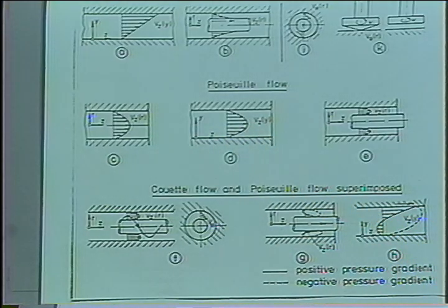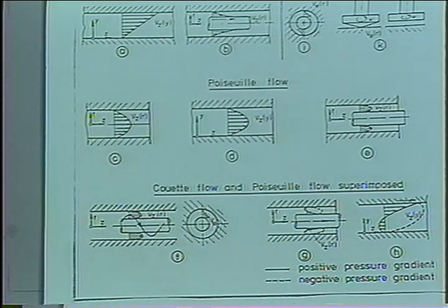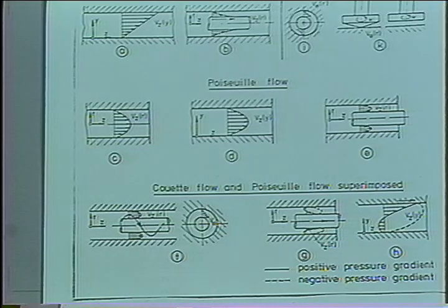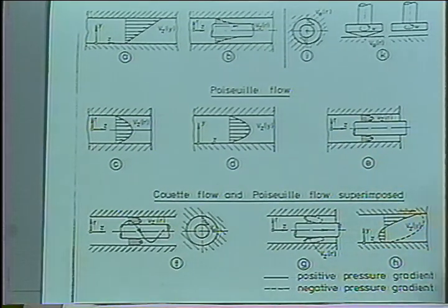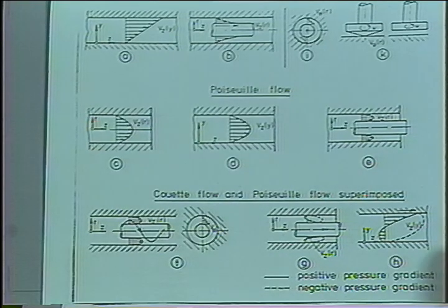Again, all of those flows are described by the same material properties, the material properties of shear flow. So if we measure the behavior in one shear geometry, then we can use that measured material function, it's called the shear viscosity, to model and to predict shear flows in all those geometries. And that's what's been done in polymer processing, for instance. So we will discuss a little more time on the shear behavior. I will go into further detail because of the importance of shear flow.